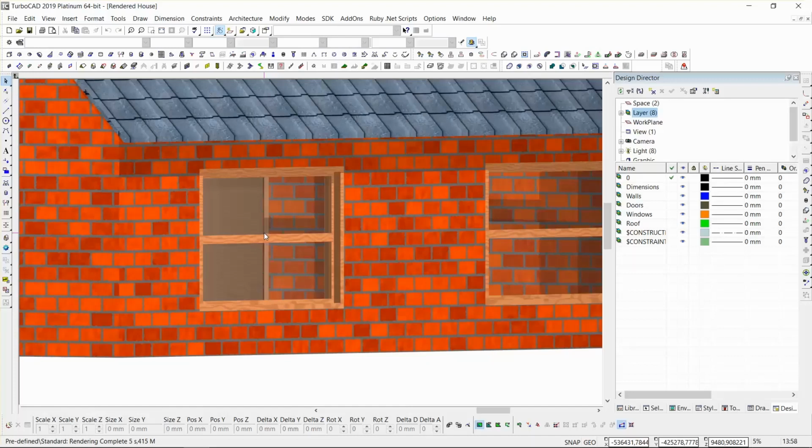So what you can do in TurboCAD is on a slope, on a terrain, if you've got a terrain, you can draw a 2D profile of wherever it should be flattened, and you can use that 2D profile and then just draw on top of that. It will automatically take out all the material that's above that. Okay, you pick up all the variances on the level. You will have to draw them and you physically change your Z level on each one. Okay, I think I can start.